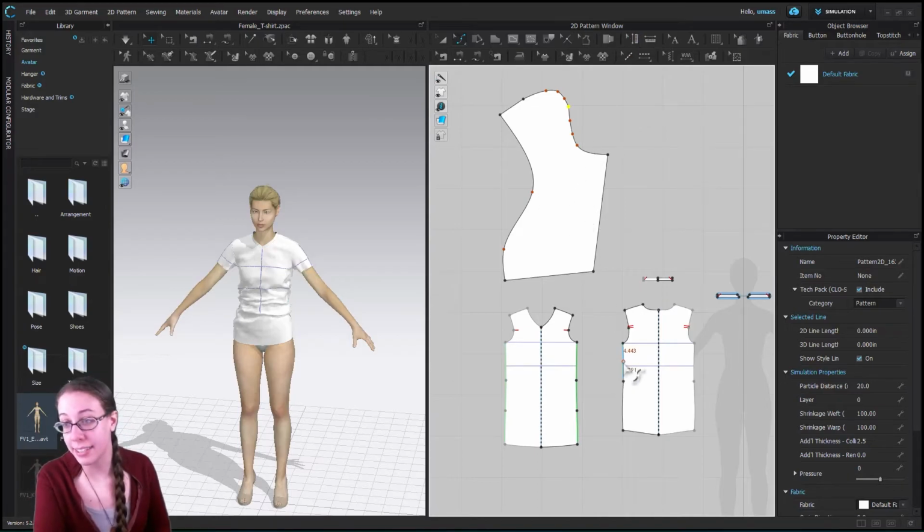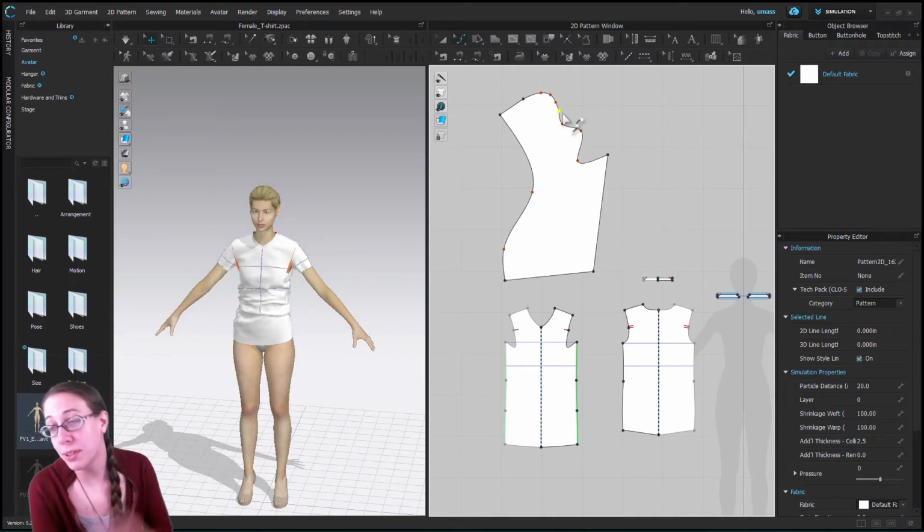Bezier points have handles like these. Handles affect the curve. Curve points don't have handles. They are the curve, and they affect each other when you adjust where the placement is. And the handles can move whole curves with all of the curve points on them. And the segment points, these are segment points, can move the whole curve.